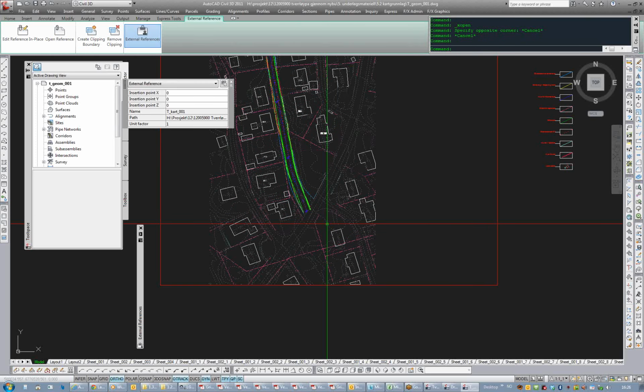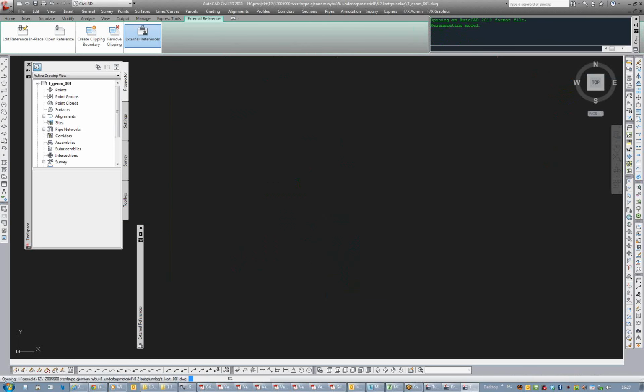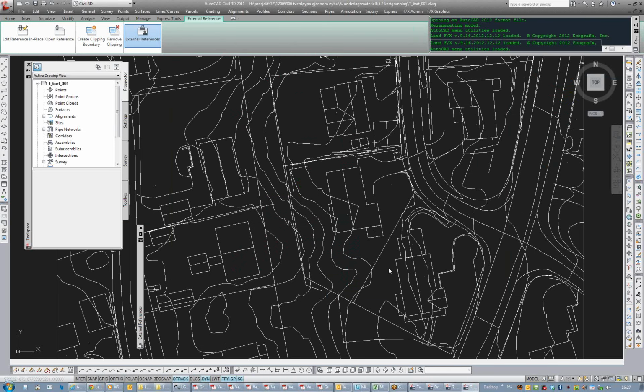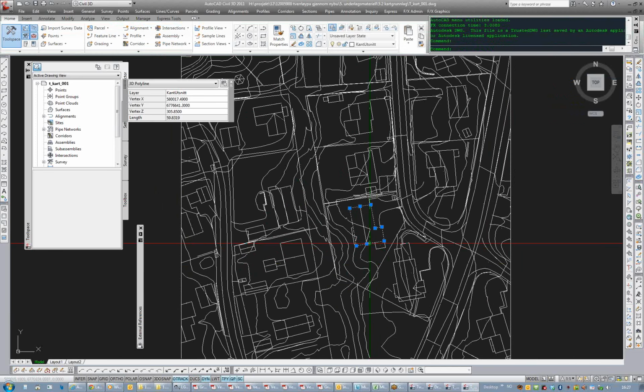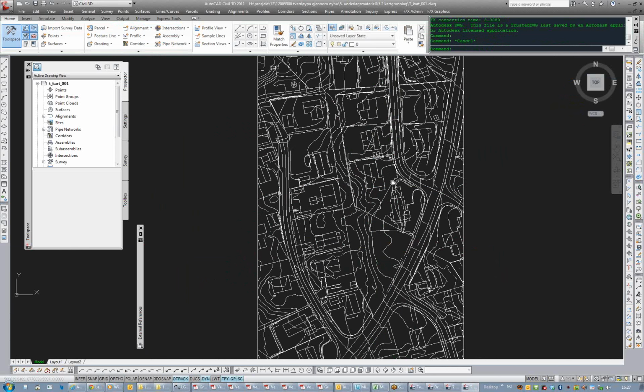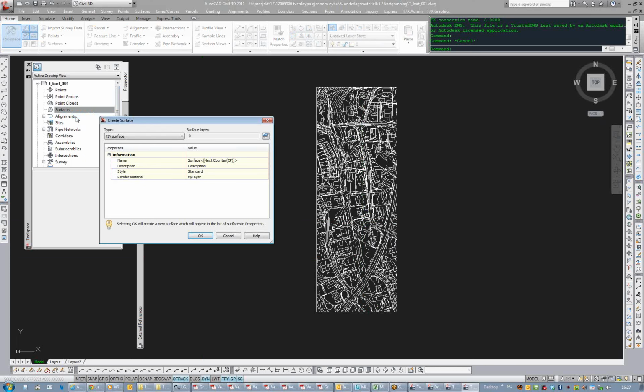I would create each surface in the drawing where those contours are. Okay. And then create the data shortcuts folder for that project. Okay, so now I would just make one from here, right? Yep. And that would just be surfaces, create a surface.